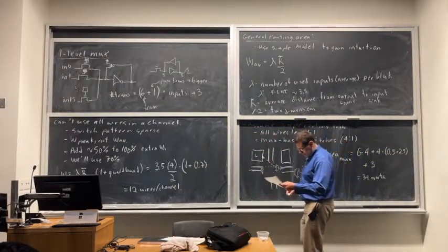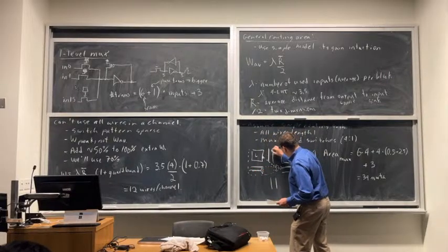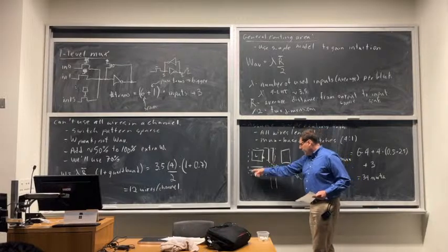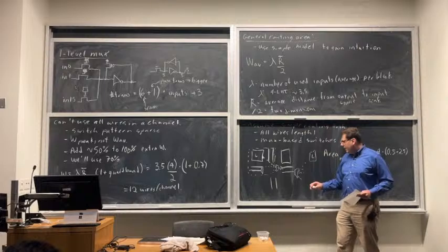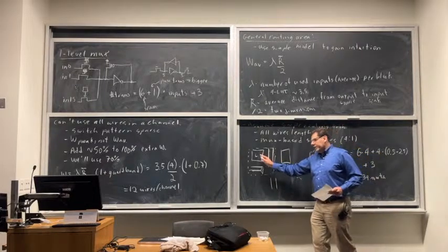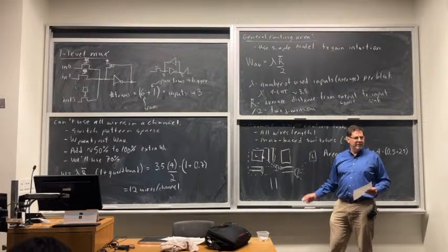So I need to take the repeated layout patterns. Basically, I need to get all the muxes that are driving this horizontal piece of channel or this vertical piece of channel. Because if I repeat that over and over again, I will get a full array of LUTs surrounded on all sides by routing channels. So I need to figure out how many muxes I have here.